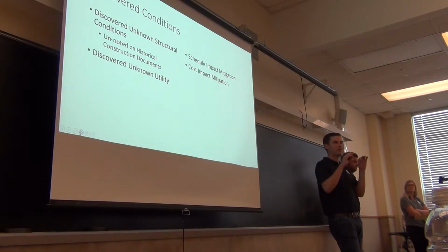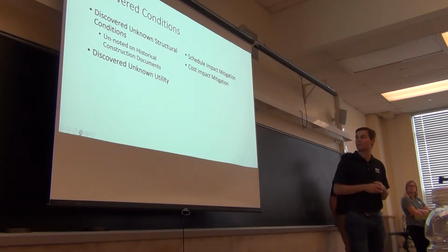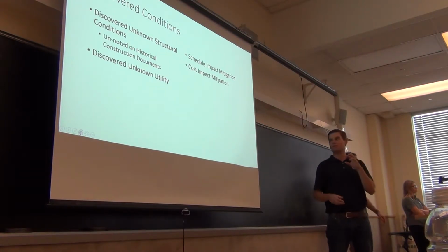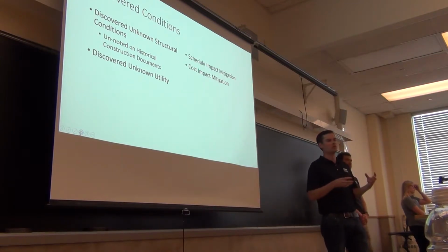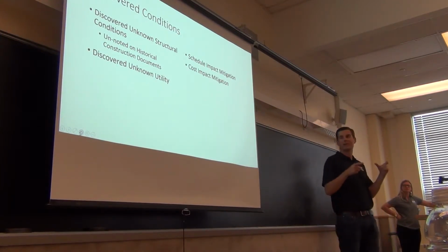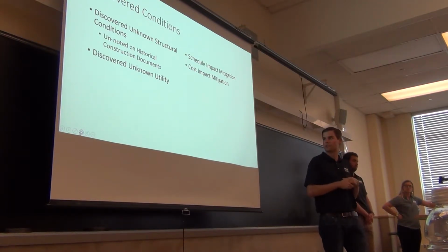Until we got up on top, there was no way to see that there was actually a splice condition there, which changed that condition entirely. Before we were able to proceed with the fully designed shoring structure, we had to do a sort of supplemental shoring, go up there, turn off the electrified third rail, and replace structural steel so that we knew that it was adequate to support then under the shore condition.